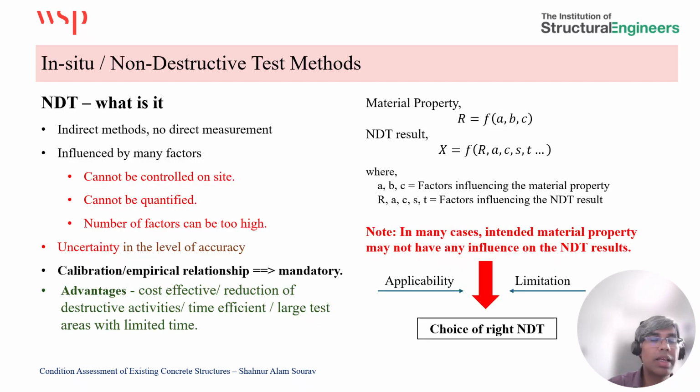During the diagnosis phase, we need to come up with a plan for how and which type of in situ testing we need to employ. This slide shows a little about non-destructive testing methods. Non-destructive testing does not provide direct measurements. It can provide some properties, but may not necessarily give any indication of the defect, its cause, or the property we are trying to measure.